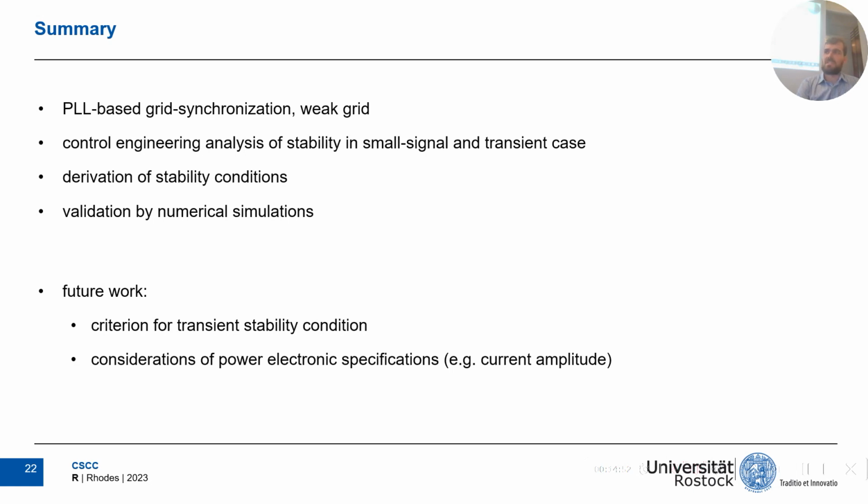This transient stability condition is not really satisfying because you have to perform a simulation to know what happens. So it would be really useful to have a criterion that shows whether this condition is met without performing simulation tests.